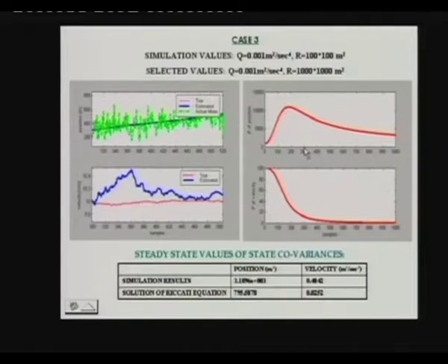Actually at 300 this is far from converged, so you cannot really expect a zero mean. The filter is still coming down, especially the effects of P0 etc. are still getting reduced. And now interestingly, look at these Riccati equation values. See, the position uncertainty steady state, previously it was 40, then it became 140, now it is 800.